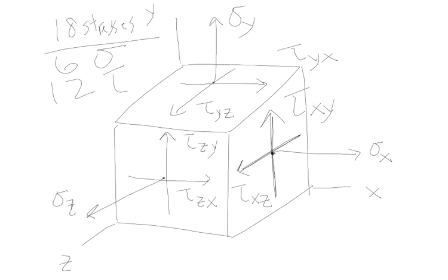Keep in mind that mechanics of materials is essentially an extension of statics. What that means is everything we look at is in static equilibrium, and the equations of static equilibrium still have to hold true. If you think back to your 3D equations of equilibrium, you need the sum of forces in the x, y, and z directions equal to 0. That's 3 equations. And then you need the sum of moments about the x, y, and z axes equal to 0. That gives you 3 more equations, so you've got 6 equations of equilibrium that you must satisfy.